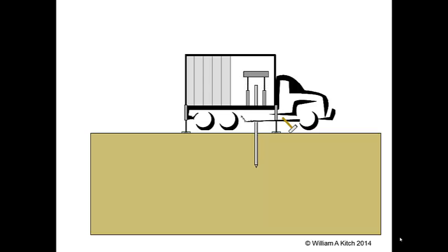resistance and side friction data. We stop the cone at some deeper depth and generate another shear wave and repeat the measurements, this time determining L sub S2 and T sub S2. This time we can compute the average shear wave velocity for the soil between the first measurement point and the second measurement point, that is V sub S2, as the difference in the two travel distances divided by the difference in arrival times, as shown here.